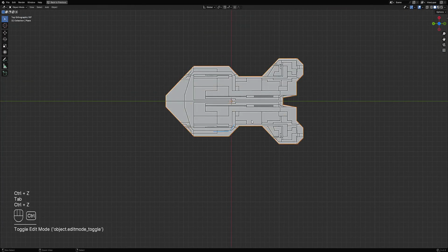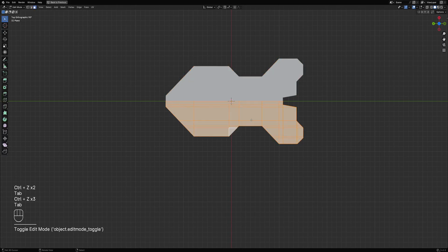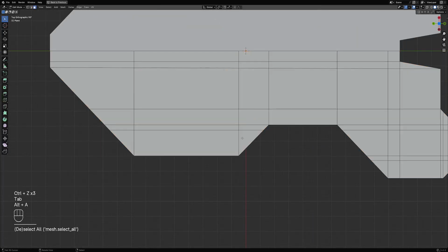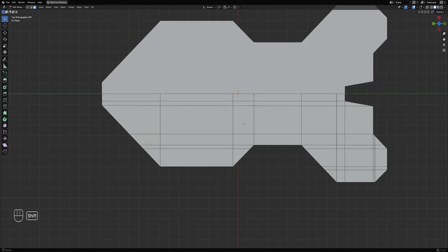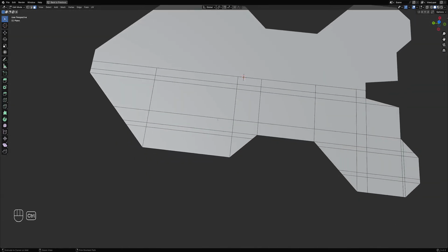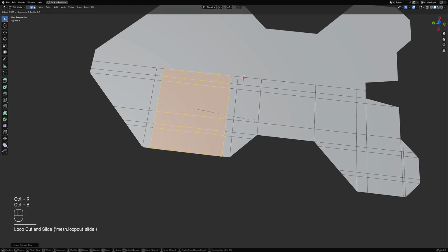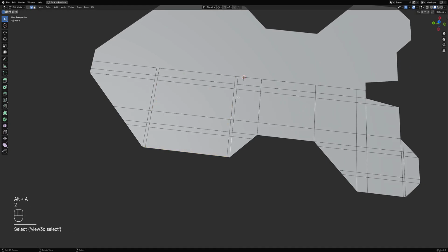That's the triangle faces. If you have time, we can also quadrify this by doing something like this and deleting this, or maybe just this first, then dissolve verts and the rest. So this becomes a quad. F9, do not dissolve verts, and then delete the rest.